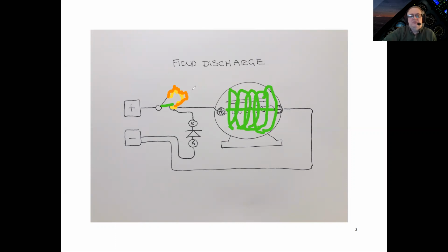So let's start when everything is good, when the switch is closed and there's a field around the inductor. The current is flowing through the switch. Let me just follow it this way. It flows through the switch, comes down, stops there because the cathode is blocking, flows through the load, down, and out to the negative terminal.